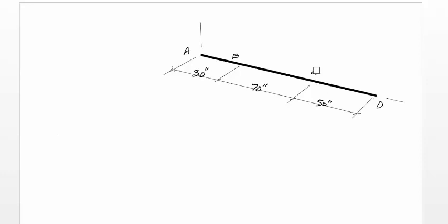We can keep the forces on the top of gear C and on the side of gear B, or replace them with the force and couple at center of the axle AD. I'm going to choose the second option. Therefore, we are going to have a force F equal to 900 pounds applied to the center of the shaft.